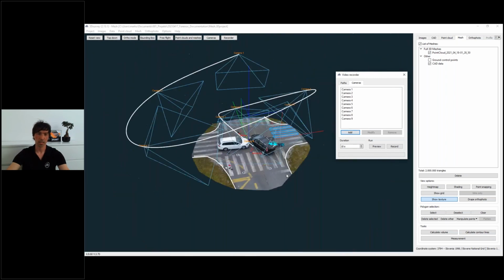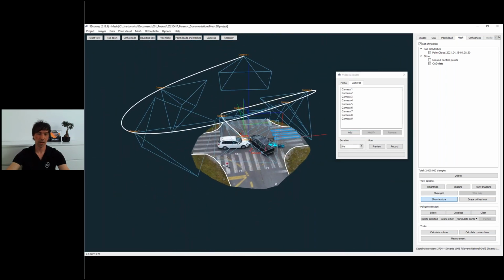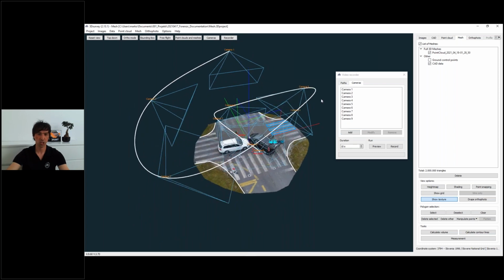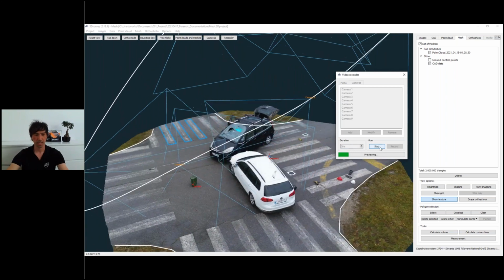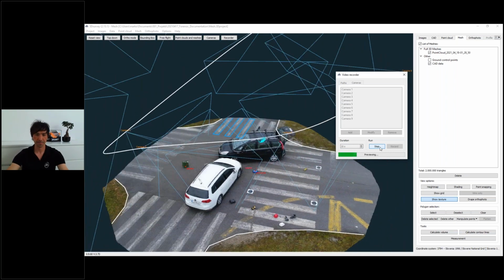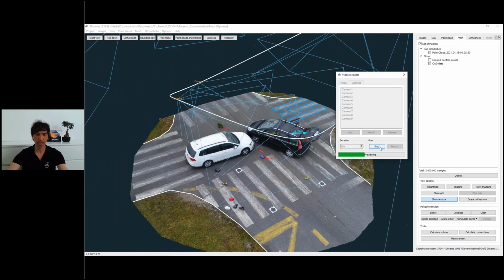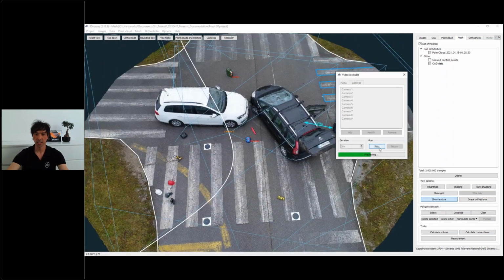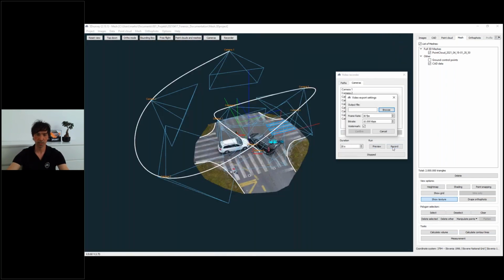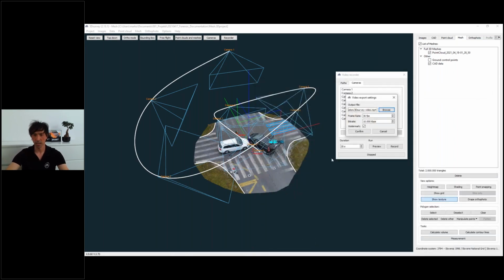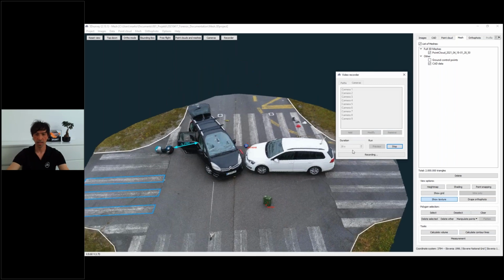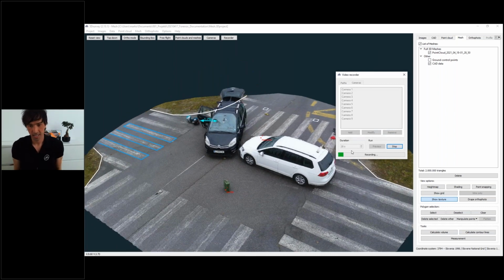and out. And you can see probably here my camera positions, the white line is showing how the camera will fly. The total duration should be, let's say, 20 seconds. And I can go in a preview mode and then immediately see how fast it is. I see the speed is okay, the perspective is fine. Let's stop the preview and start recording mode. So yes, this is okay. Confirm, and right now we are recording this.